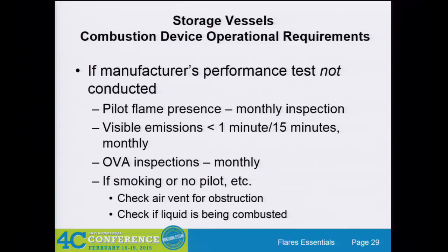Okay, storage vessel combustion device requirements. If the manufacturer performance test is not conducted, then you have to do some inspections. They're pretty basic inspections. Pilot flame presence, you know, this is when your record keeping is really going to come in. You've got to do a monthly inspection. You've got to make sure your visible emissions, you're not smoking. OVA, visual inspections monthly, and again, if smoking or no pilot light, you've got to correct that situation. So if you don't have a manufacturer's performance test, you're going to be obligated to do some record keeping.